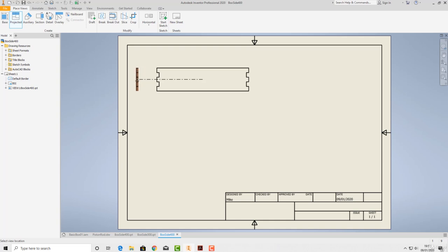Okay, so what I'm going to do is put the left hand side there, and now if we move diagonally down, you can see we get a kind of 3D representation, and depending which one you want to see, which one you think looks best, I'm going to use this one, so I'm going to click there. Okay, now right click and click create, and you should get those views. If you didn't get those views, rewind it and watch that again.